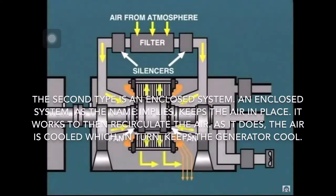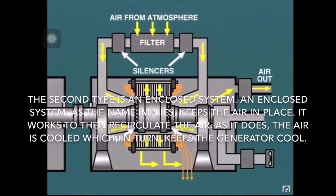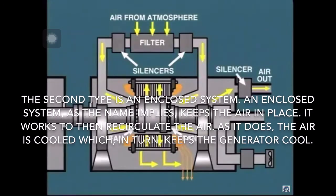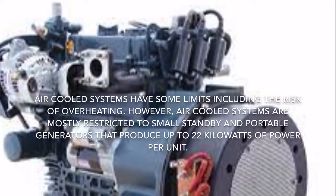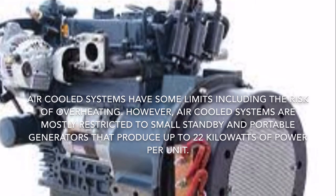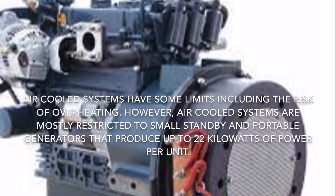The second type is an enclosed system. An enclosed system, as the name implies, keeps the air in place. It works to recirculate the air. As it does, the air is cooled, which, in turn, keeps the generator cool. Air-cooled systems have some limits, including the risk of overheating. However, air-cooled systems are mostly restricted to small standby and portable generators that produce up to 22 kilowatts of power per unit.